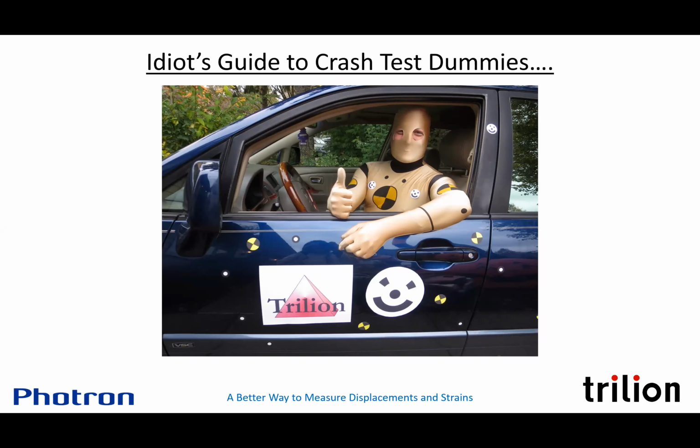Okay. Another question. How is the performance of these high-speed cameras on shiny surfaces like polished metallic surfaces? Is it needed to spray them? Right. If it's regarding can we do DIC, typically we would want to do a flat base coat. Normally we would use flat white spray paint. There are more removable patterns you can use. Developer spray, which is used for crack inspection, is very commonly used as a removable way to put down a base coat that would get rid of the specular reflections.